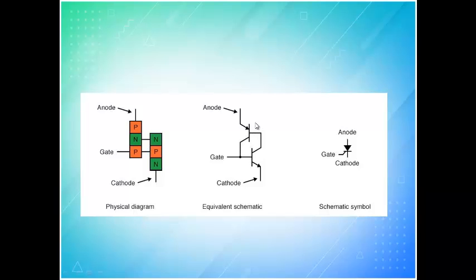Compared to a transistor, the advantage we obtain in SCR is that if you trigger lightly, that is more than sufficient. You don't need to trigger more, because the light trigger itself moves through, the output is brought back in, and it circulates such that the triggering gets amplified. That is the advantage over our previous case, and this is the symbol of SCR. I repeat, it is a 2 transistor analogy, which means 2 transistors are connected back to back. The configuration is as follows.